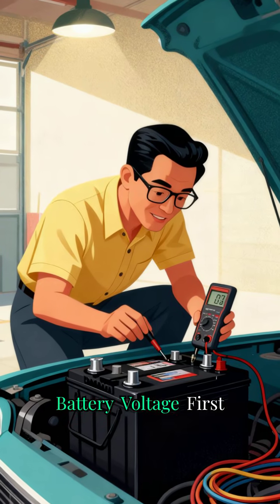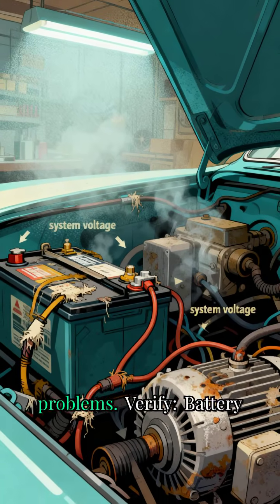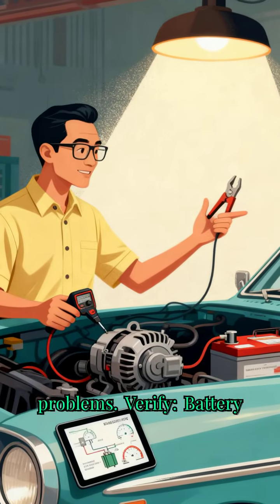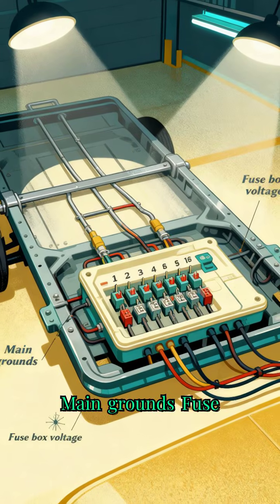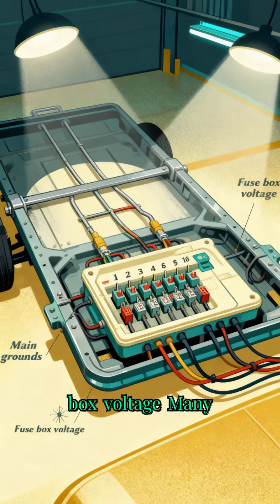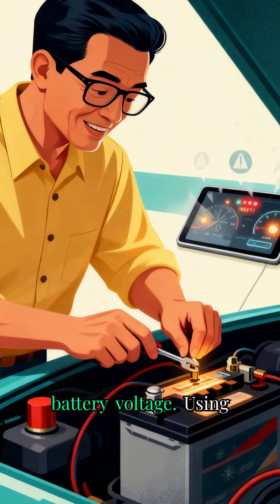Check battery voltage first. Low system voltage causes many CAN problems. Verify battery voltage, charging system, main grounds, and fuse box voltage. Many communication faults disappear after restoring proper battery voltage.